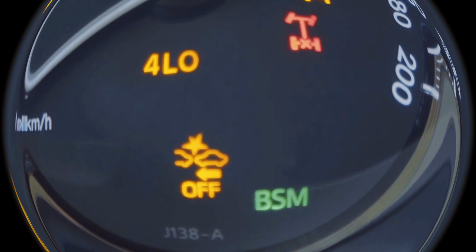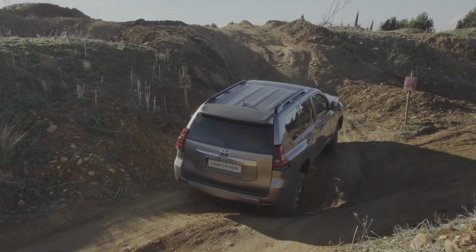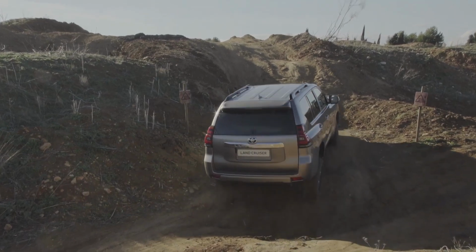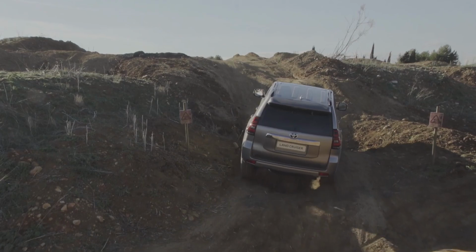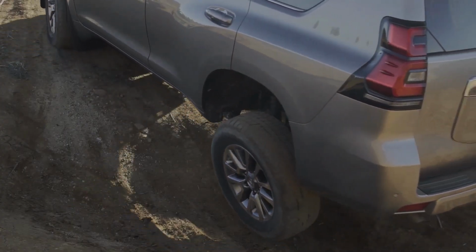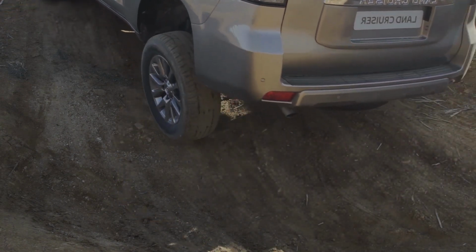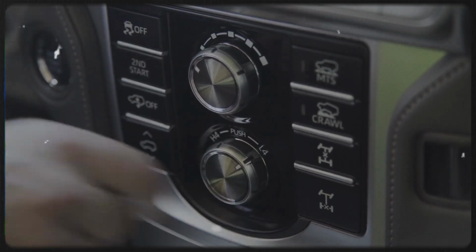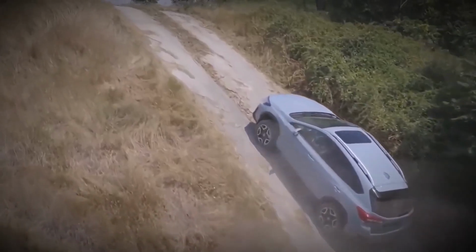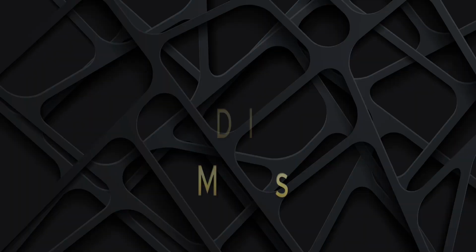If one wheel loses traction, a standard differential compensates by increasing its rotation speed, which can lead to the other wheel becoming immobilized. This situation can cause a loss of control in challenging road conditions. Differential locking can be full, transferring all torque to the wheel with traction, or partial, distributing torque proportionally based on road conditions. Locking can be manual, activated by the driver, or automatic, controlled by electronic systems that monitor driving parameters and engage the lock when needed.